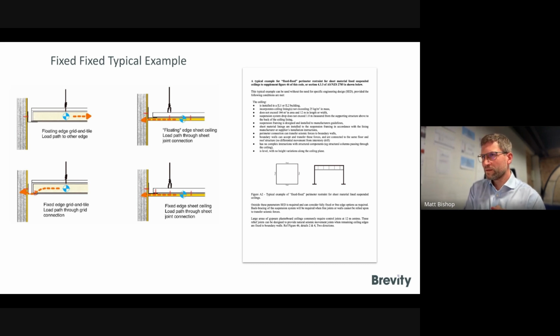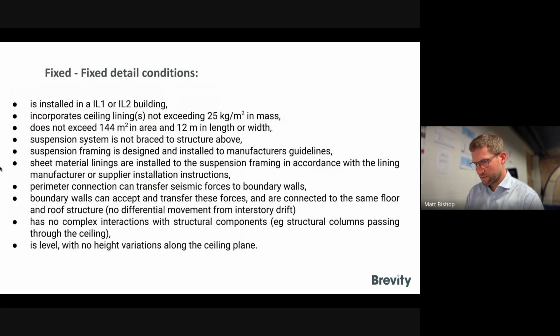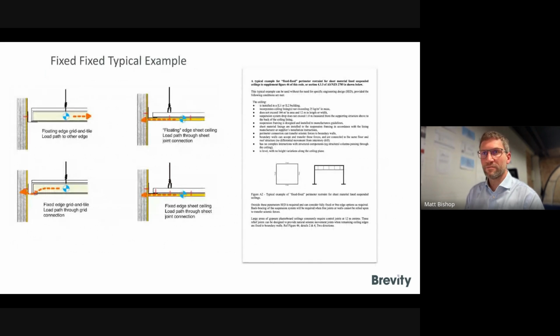floating? And when they do tests on the strength of this, when they do tests on this floating joint here, they find out that it doesn't float at all. And if they're following their standard square stop detail, they're actually getting more strength in that connection than they are out of our fixed connection. And that leads us to go, okay, these ceilings are effectively fixed. Always have been.